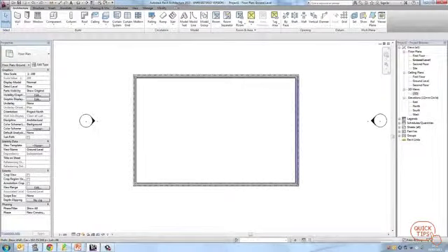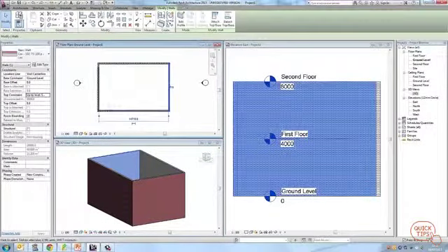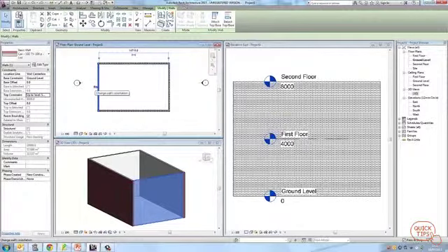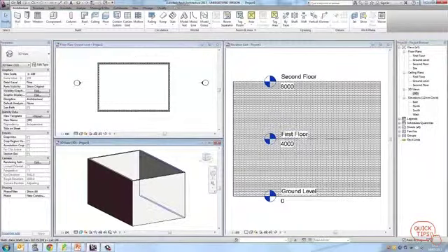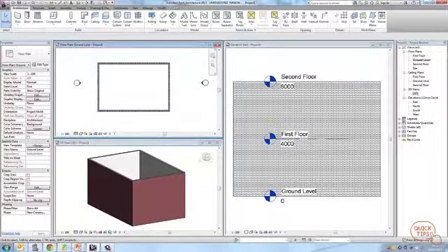So now, press WT for window tile again. If you look at your building, you can see there's white inside the cavity and then the brick on the outside. If your wall does happen to have the white on the outside, if I click onto this wall here and press this little arrow here, it'll change the orientation of the wall. So it'll change the white side to the outside, but we don't want that. It's just in case you happen to have done something and it changed the orientation. So let's change that back. That's how it should look.